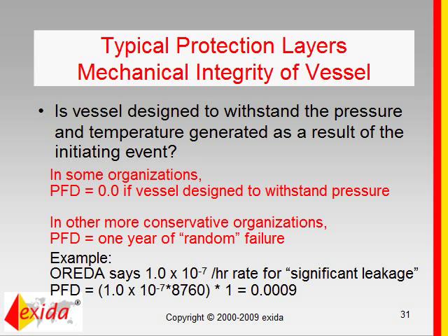And why is it important for many end users to do that? Implementing a SIL 1 safety function is, I'd say, relatively cheap. In the majority of cases, that just means a single transmitter, a single valve. If we talk about a SIL 2 or SIL 3 safety function, then you probably end up with redundant inputs and redundant outputs, and that could become very costly, not just from an initial purchase perspective, but also from a lifecycle cost perspective.